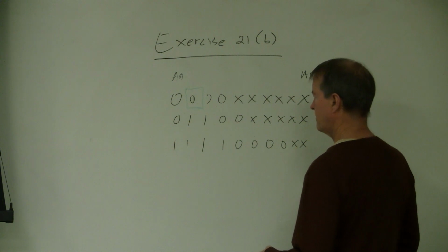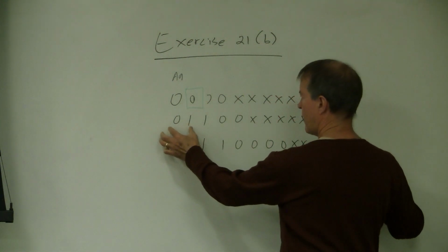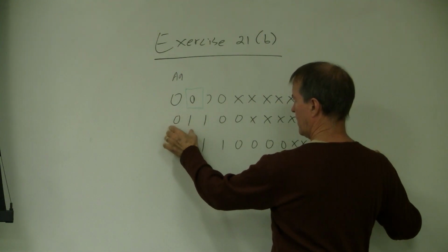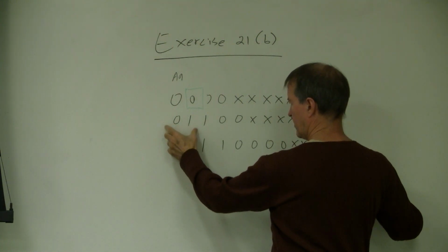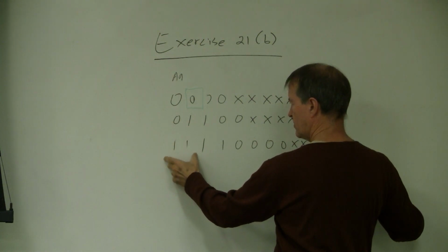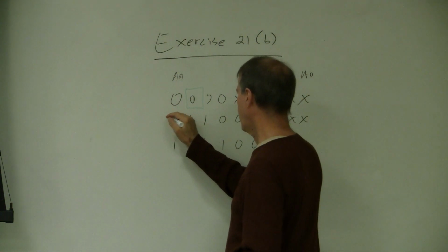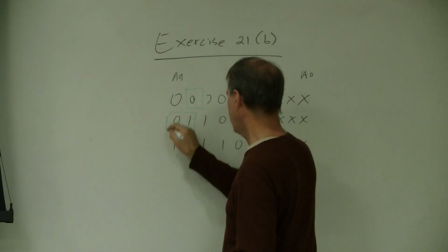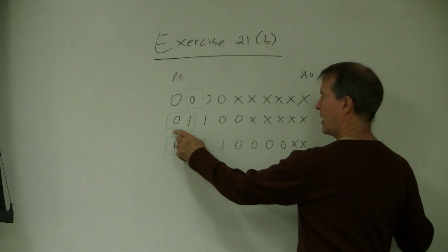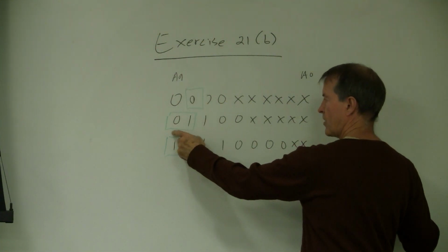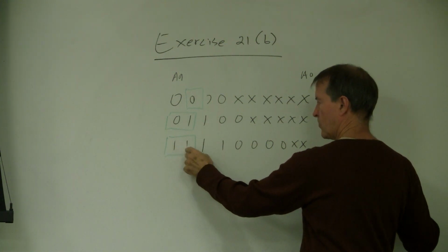So now, yeah, there's a couple of ways to do this. So now, I guess, then what did you do? Did you do these two? Yeah. Like this? Exactly. So if the first 2 bits, first 2 values on the address line are 0, 1, then we select this chip, and if the first 2 ones are 1, 1, then we select this chip.